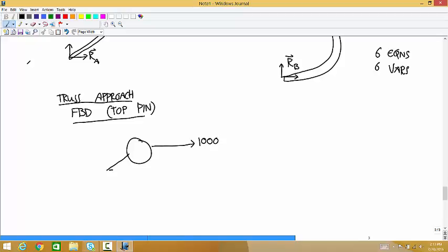You have the tension F1. And now what's the direction of the tension F2 on this pin? That's the thing that's a little unusual with this. But think about the definition of a two-force body. Yep, it's straight down towards the other joint.